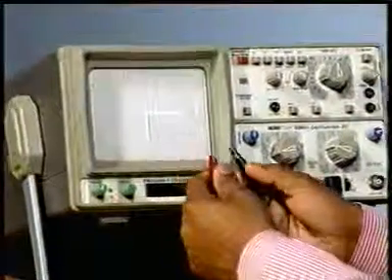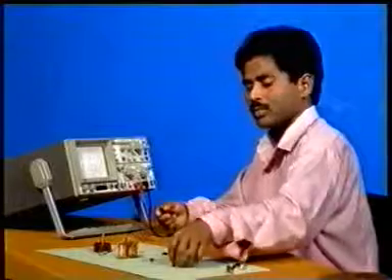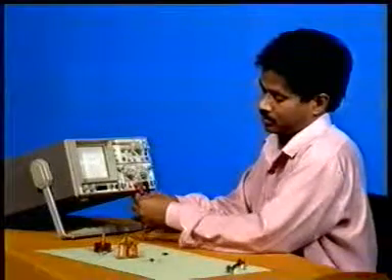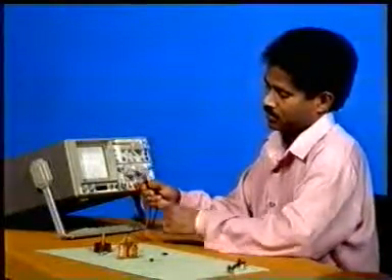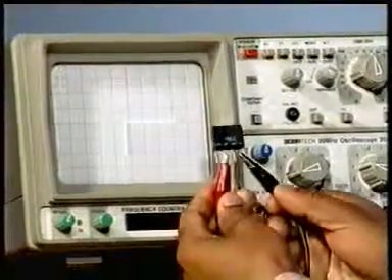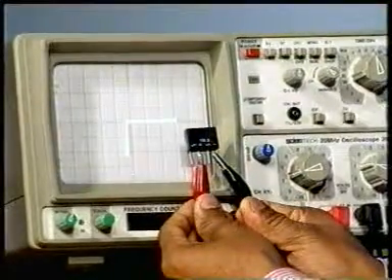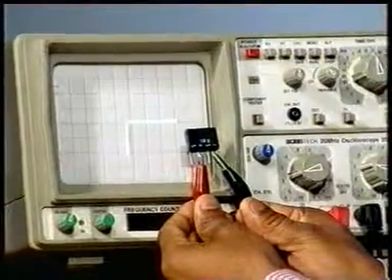Fine. And now a rectifier. Okay. And now in case of rectifier, since the input is AC, we will only see the output, that is between terminals 2 and 4. Yes, sir. Yes. So you are getting a figure like this. This shows that the rectifier is healthy.